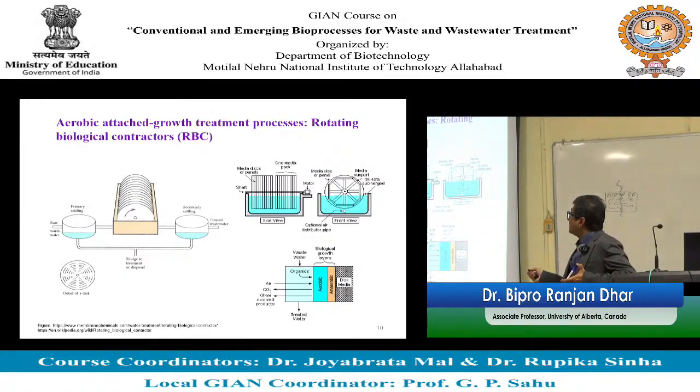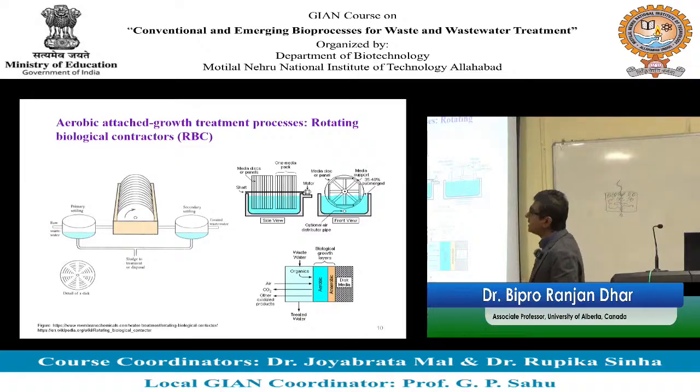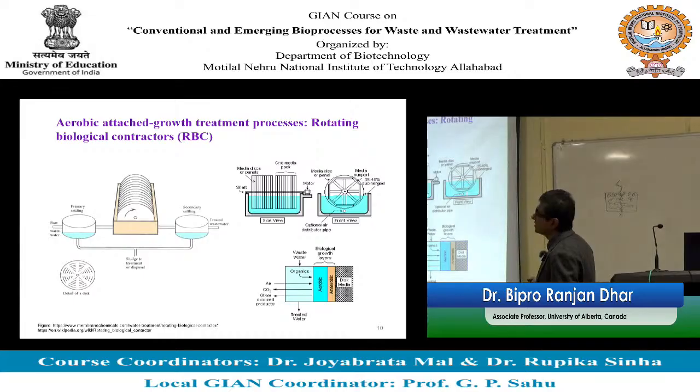This kind of system, you don't provide active aeration. You don't need to continuously supply oxygen because it's rotating, so there is going to be some diffusion of oxygen in the wastewater, or inside the biofilm, and that's going to actually facilitate the process. And for this kind of system, the media panel is actually 30 to 40% submerged. It's not going to be completely submerged.